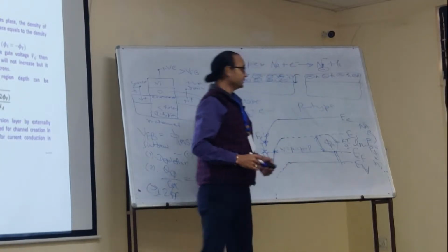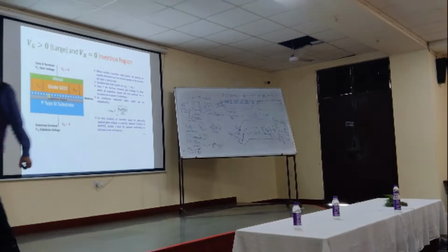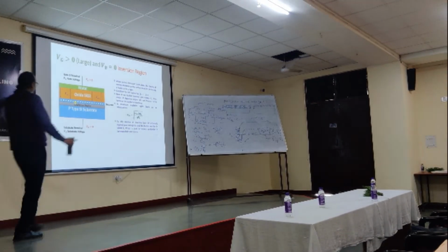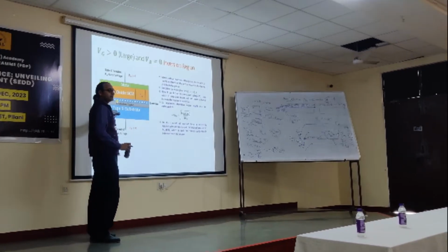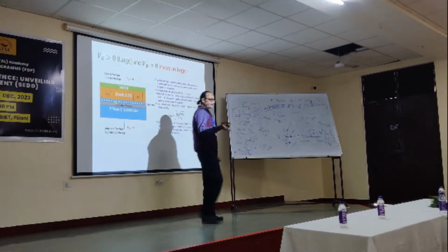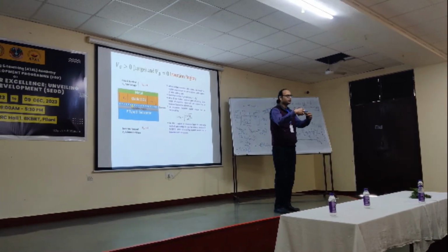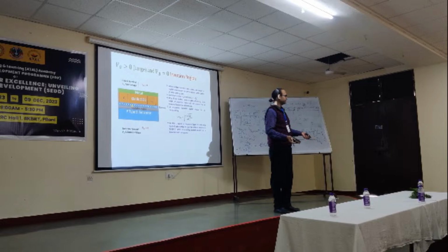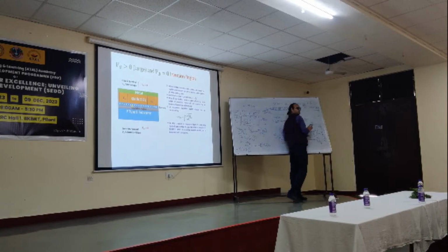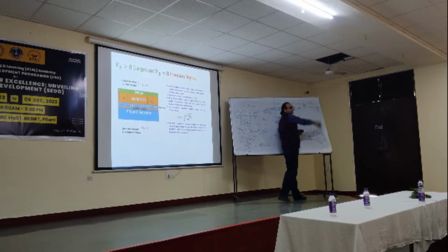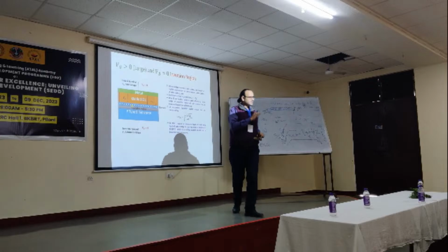Now, what is happening? As I did earlier, electrons are coming from the gate side into the p type substrate. This is a common tendency: whenever an electron approaches a hole, it will get recombined and represent a neutral atom. Neutral means no charge is there now. Electron came, hole is depleted, or you can say recombined. So what is left behind? Only acceptor ions are left behind.